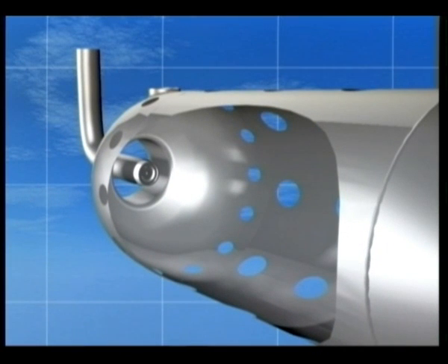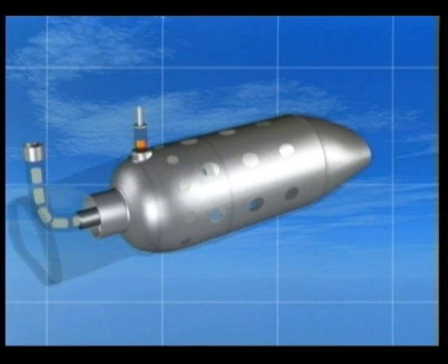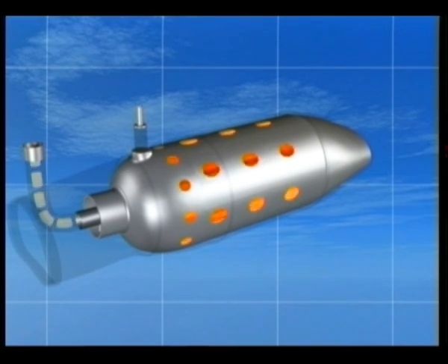Each combustion chamber is equipped with a burner containing a swirl-type atomizer, and through the atomizer the fuel is injected under pressure by the fuel pump into the combustion chamber, where it mixes as fine droplets with the incoming primary air. The combustible mixture formed is ignited by the igniters in 2 or 3 of the combustion chambers, depending on the design of the engine. On completion of the starting cycle, the igniters are cut off. At this stage, we can say that we have light-up.